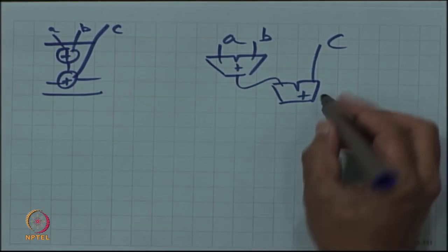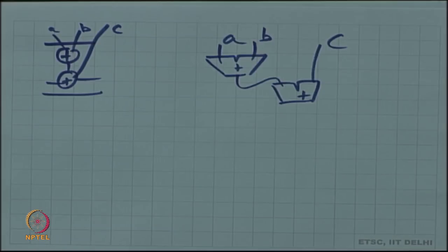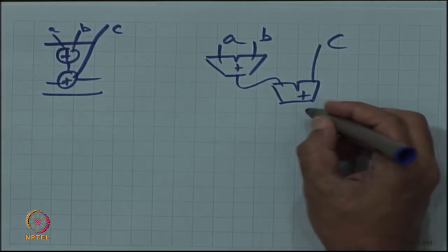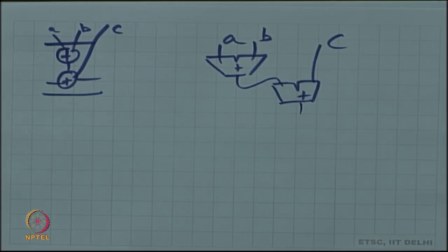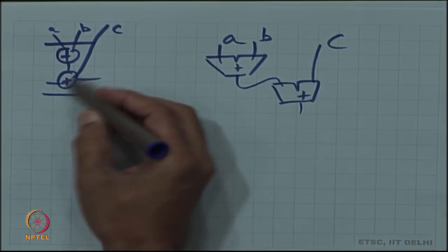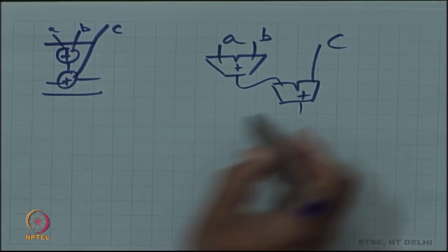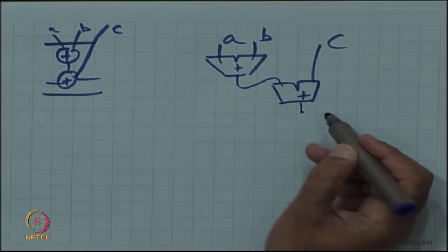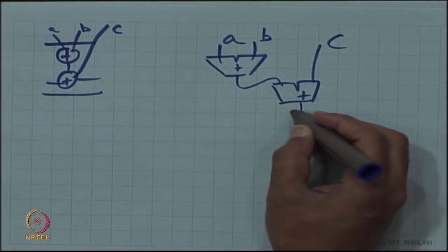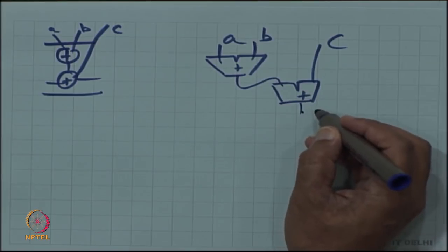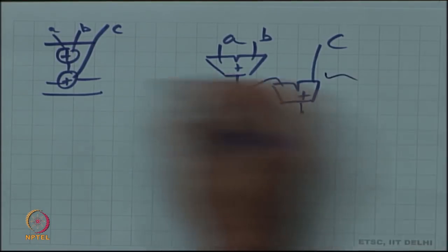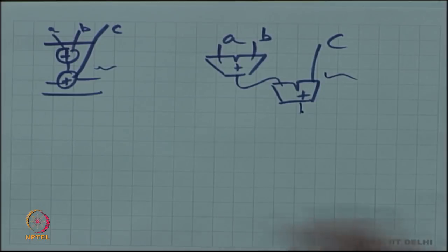So when is this second adder looking at its input? We are sampling the output only after the cycle, and that's fine for us. This is a combinational circuit. It is looking at its input all the time, but the point of the schedule is just to make sure that by the end of the clock cycle, we have the right value on the output. It is giving us incorrect results somewhere in the middle of the clock cycle, but that is okay.